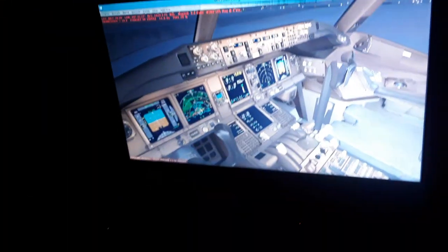We have the General Electric GE90 turbofan engine installed on this Boeing 777-300ER. It's a jet airliner. So we have a lot of thrust, one on the left wing, one on the right wing, symmetrical thrust. The engine contains a gearbox, and the FADECs, the full authority digital electronic control computers, one installed per engine, control, monitor and display the upper and the lower EICAS indications that you see, like the N1.